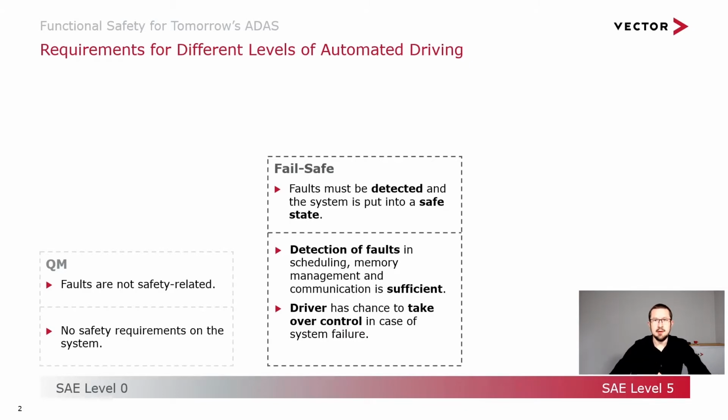Let's take a quick example of a power steering ECU. If your power steering ECU fails in a way that is not recoverable, then the power steering ECU shuts down, all the outputs turn off, your steering goes very heavy in the car, and you get a steering warning light on the dashboard, but the driver has the opportunity to pull the car over to the side of the road. Now, of course, that is an undesirable state for the ECU in the car to be in, but it's considered to be a safe state.